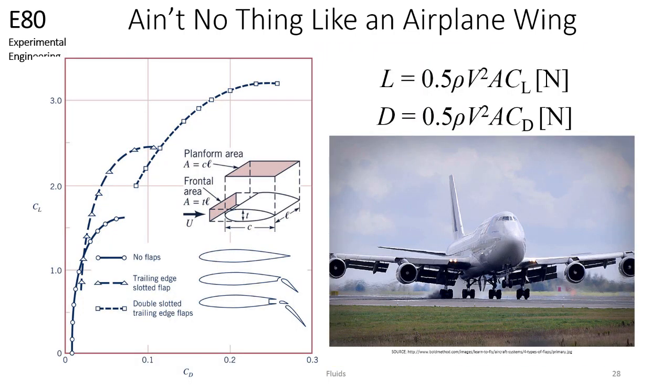This slide is an example of how the lift coefficient and drag coefficient are used to model the complex dependencies on the lift and drag of an object, which include shape, flow conditions, and inclination. In this graph, you can see that the coefficient of lift can be increased at a certain angle of attack just by changing the shape of a wing. However, there is a trade-off. Wing shapes that generate a lot of lift also generate a lot of drag, since the coefficient of drag also increases with coefficient of lift as the shape of a wing is changed.